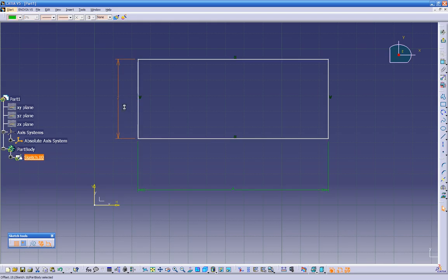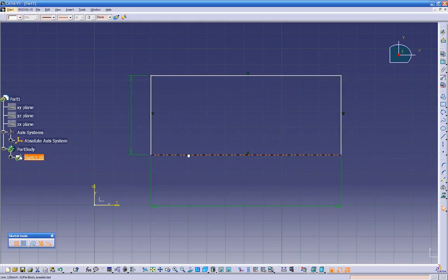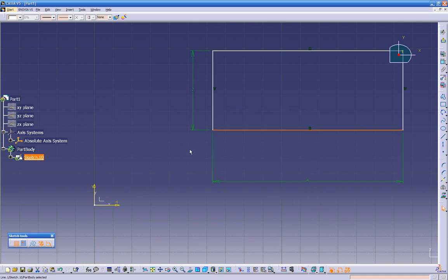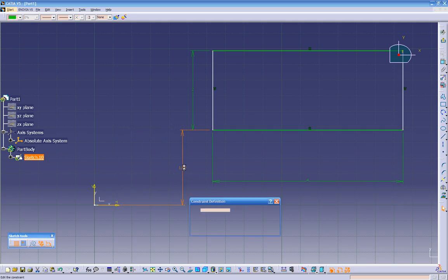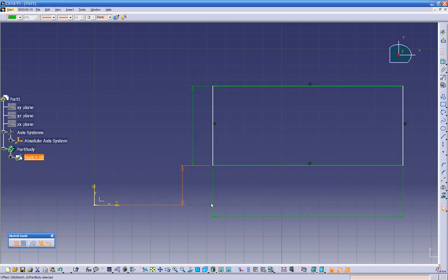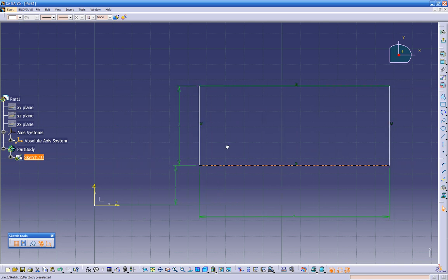It's fully constrained. The only thing that is not constrained is the axis of the sketch, which is important. So let's give it a quick dimension. See, it automatically knows it's fully dimensioned, and the moment I want to do this constraint, it knows I already have it. But if I click on the horizontal line, then it will let me put the dimension. So you can click OK, double click on the dimension, let's make this 1 inch, and see, this way I'm able to move the rectangle this way.